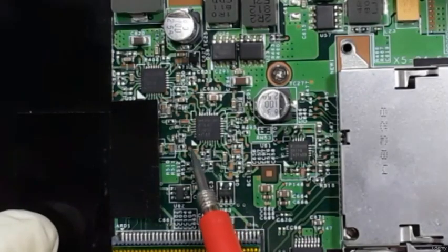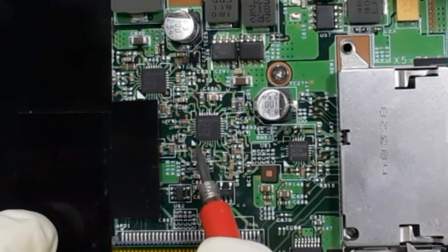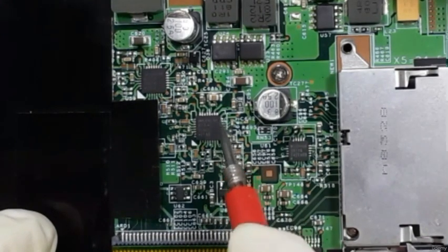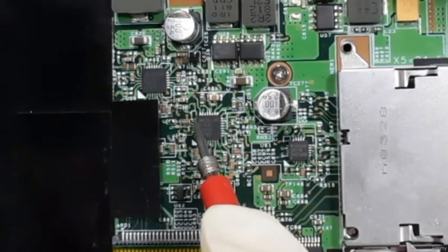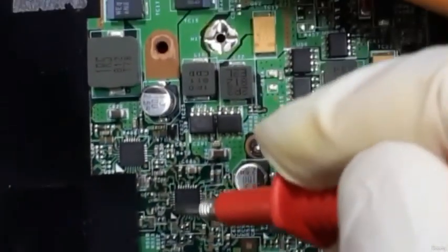So here, as you see, we have this mark, this white triangle, which means this is pin number 1. Here we have 8 pins in this side, so we have 8. Here also we have 8, so here 16, and here we have 8 over here, so this is the last one. Here is 24. The V in exists in pin 21. Okay, so let's check 21.